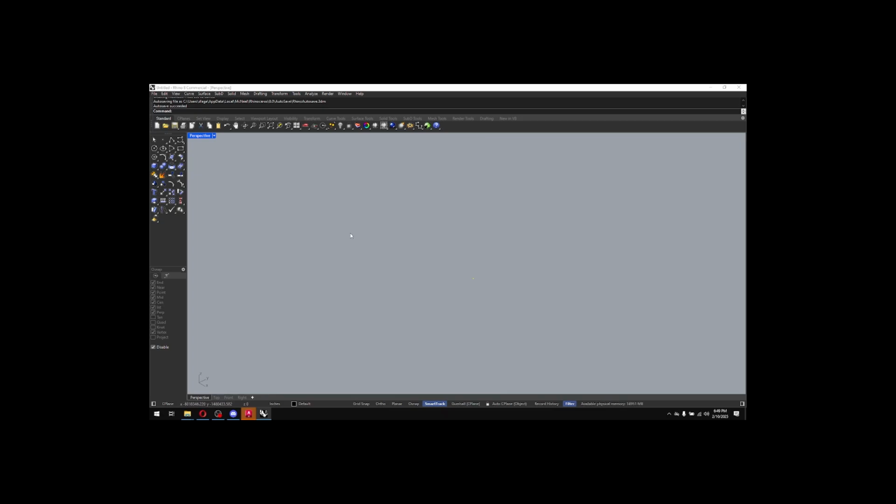Quick session on, I know we're running out of time. Just like in CAD, Z-enter starts your zoom command. A couple of these are slightly different with the shortcuts. Like if I wanted to see everything that I have in my model space in CAD, I would type Z-enter, E-enter for extents, as in it's going to zoom all the way out to the extents of my drawing. They had that one in here as well, so I can hit E-enter, and it's going to zoom all the way out. That will happen in perspective view, top view, whichever one that you're in.